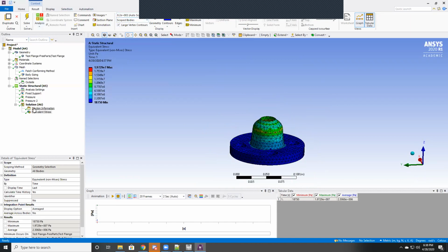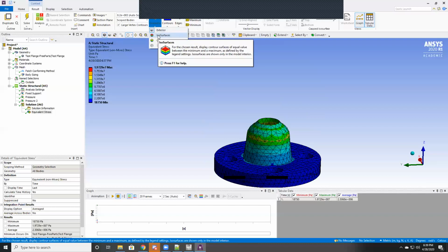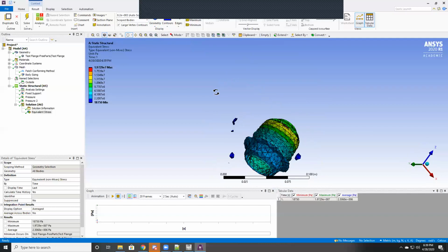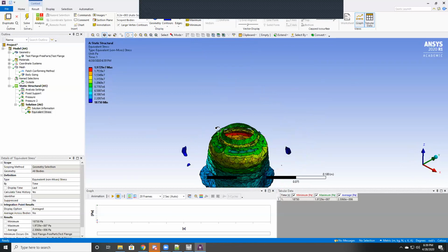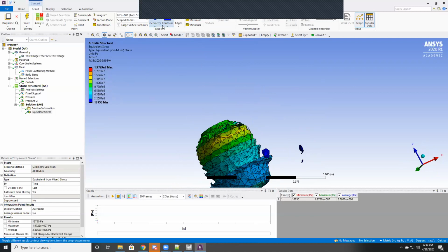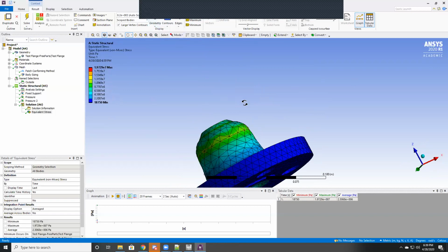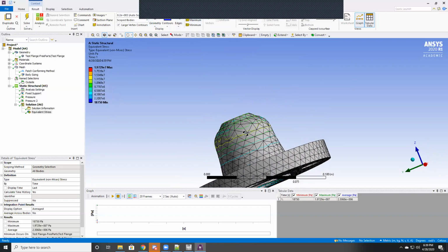We can also have it display differently, instead of just this sort of coloration of the outlines, we might want to see where the structure is on the inside. So we might change it from a geometry of just the exterior to something like isosurfaces, where now we can see all of the points in the surface where it actually matches these exact values. So you can see those walls of the cells and where those forces exist. You can also change from the exterior to smoother contours for a cleaner image, or something like iso lines to see just where the actual lines are on a face.